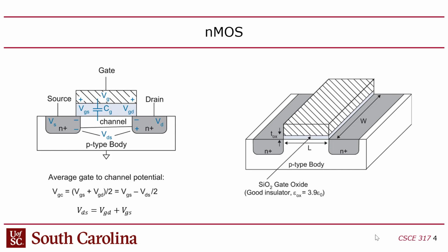Yes, but the tricky part is that the channel is weird because it's not a traditional thing that you can measure. It's not like, what is the voltage of the channel? Well, the voltage of the channel initially is going to be ground in this case, because I told you we ground the substrate and the channel is part of the substrate. But as the minority charge carriers start to collect in the channel, it will start to become decoupled from the substrate, electrically decoupled.